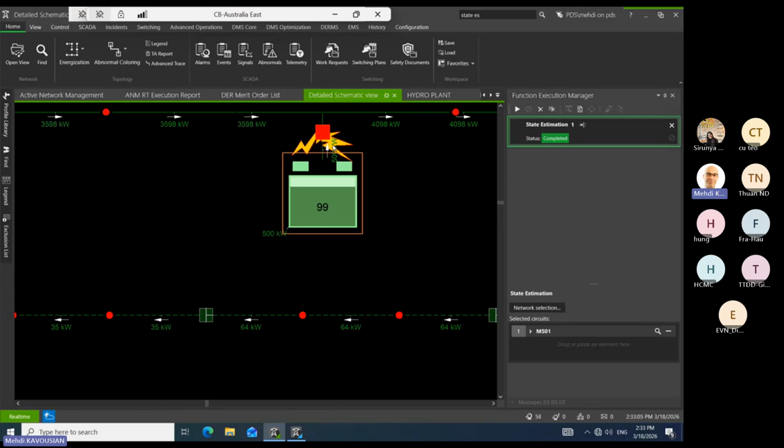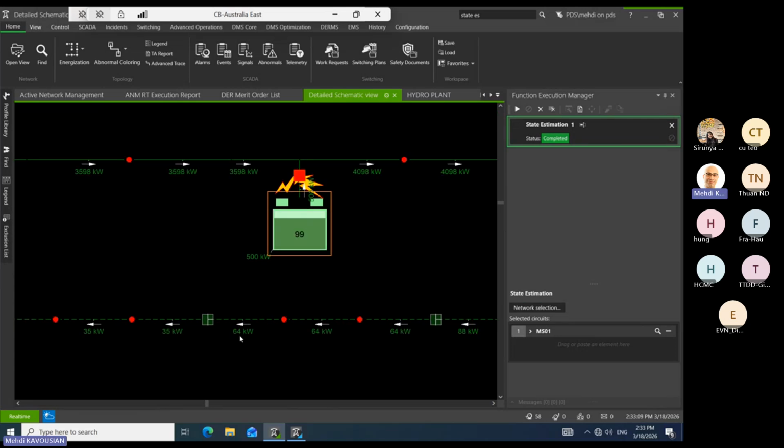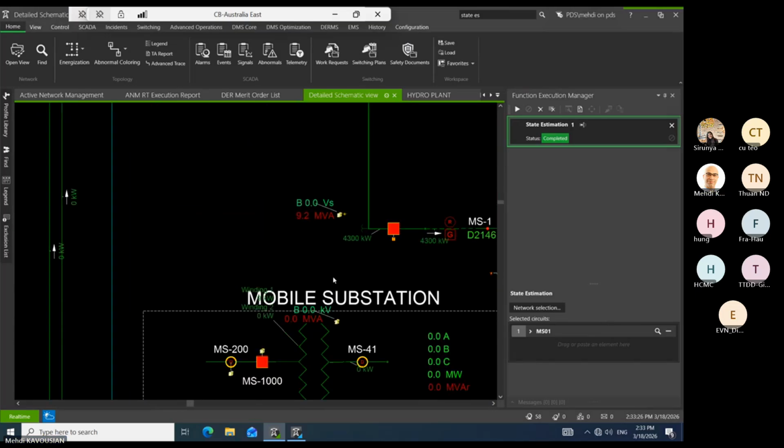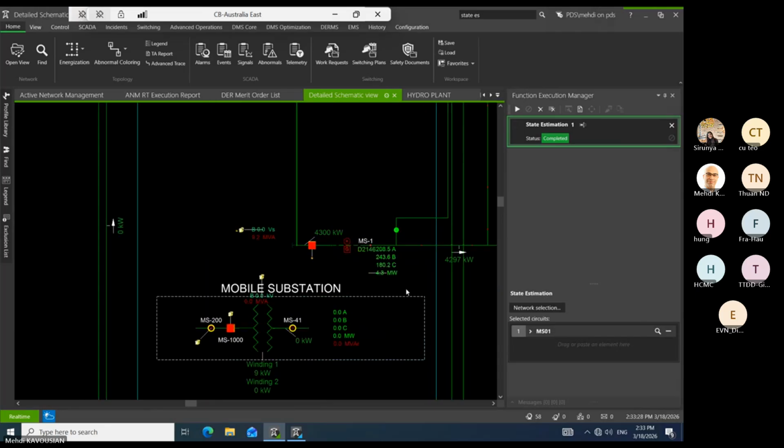These flashing ones mean it's producing, and this can change. So yes, it's producing. You see, this load is actually 4 megawatts, and this is reducing that load for the upstream. That's because we wanted to go to a lower value on the feeder head, right?